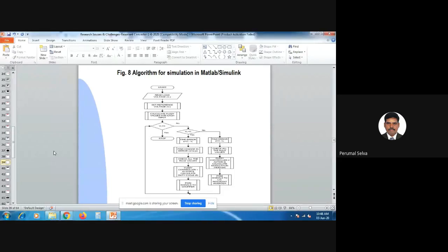If this condition is not satisfied, and VL is greater than VR, find the error, E equal to VR minus VL. Find the change in error. Check all the rule values. So fuzzy controller 1 acts and calculates duty cycle. Then PWM signals go to the chopper.